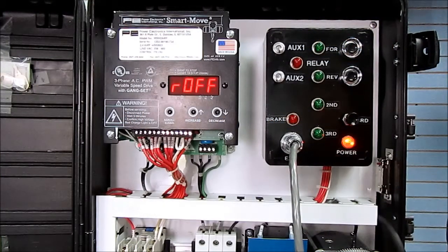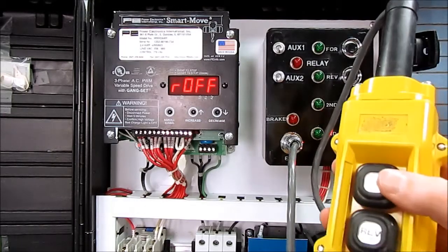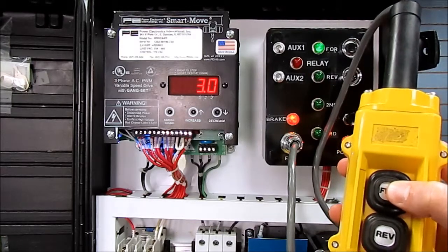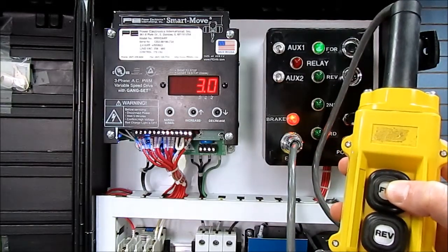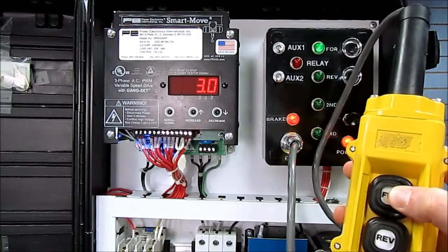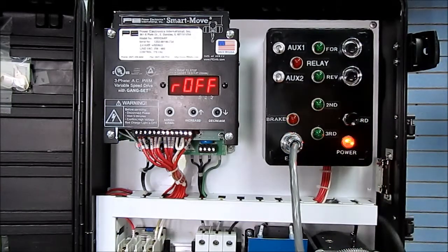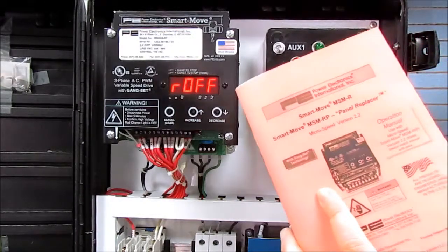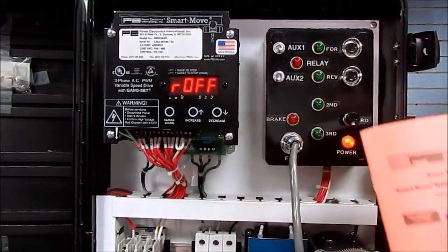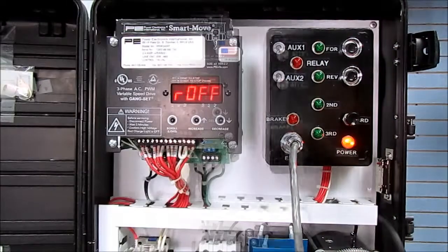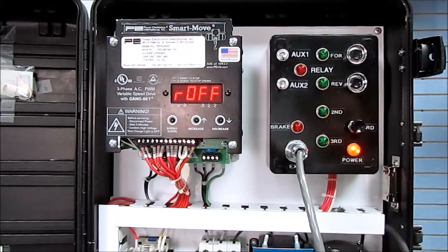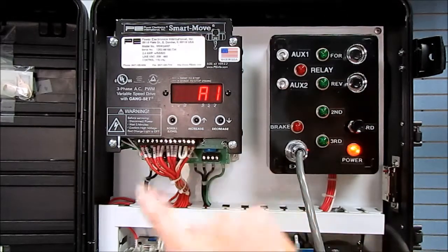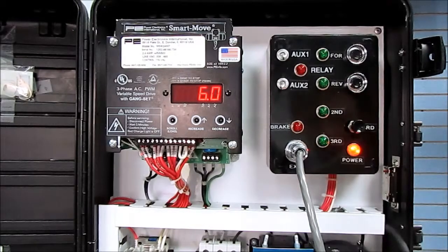This drive is controlled with a two-step pendant. Notice that while the drive is running, the screen will display the frequency in hertz at which the motor is being driven. In this case, the first step is a low speed setting of 3 hertz. Let's say that you would like to increase the speed of this setting. After consulting the user manual, you find that the low speed setting is parameter A12. To get to the desired parameter, you first hold down the scroll button until you see the letter A. Then let go of the scroll button once you see that value.